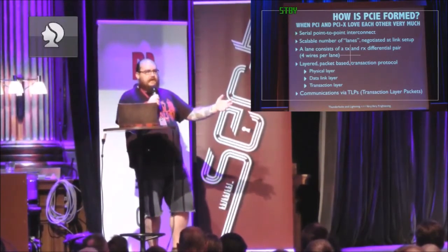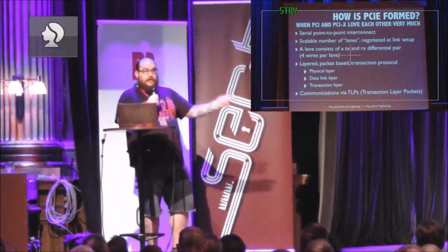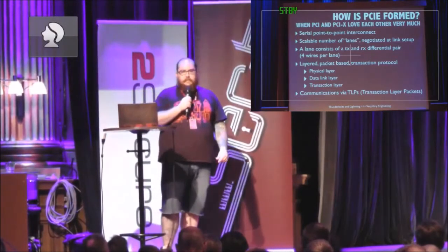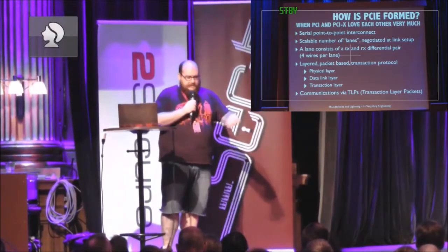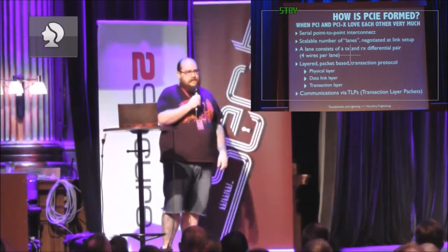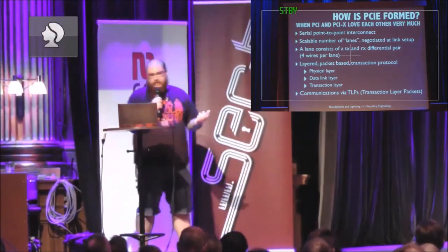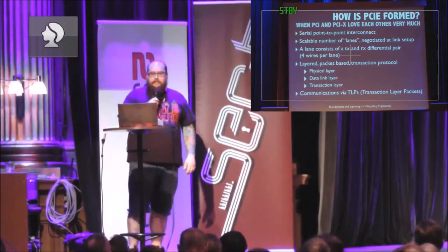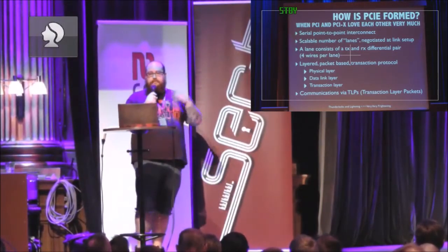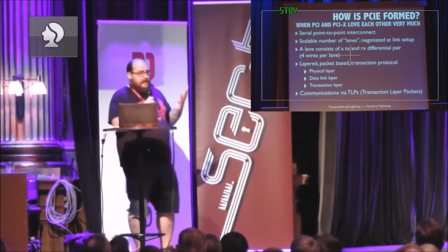So you can have a 16 lane card, and it'll just use 1 lane if that's all that's available. Say there's an electrical fault that results in 1 lane being broken, or you've sawn the end out of your 1x slot and jammed a 16x card in there, it'll still work, but it'll just negotiate at 1x, right? It's actually pretty simple electrically, because there's only 4 wires per lane,